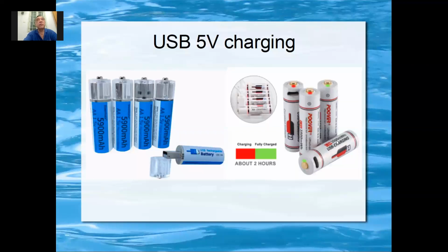Okay, here they put watt hour, here they put milliampere hour. Okay, so there's a difference. If you take this 3500 divide by 1.5 volt, then you get the milliampere hour.